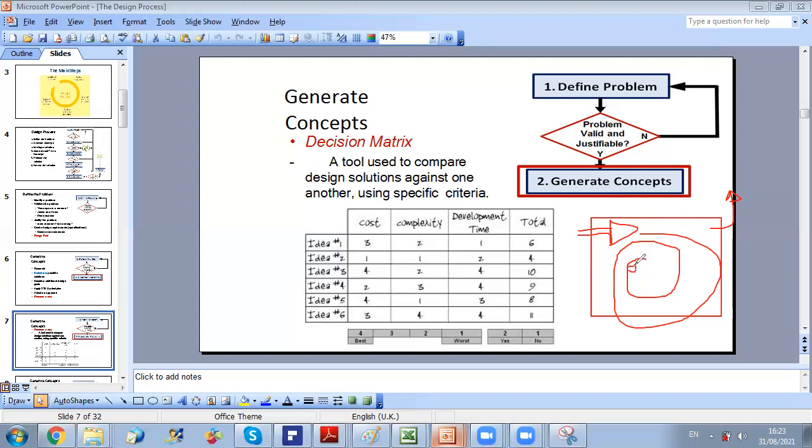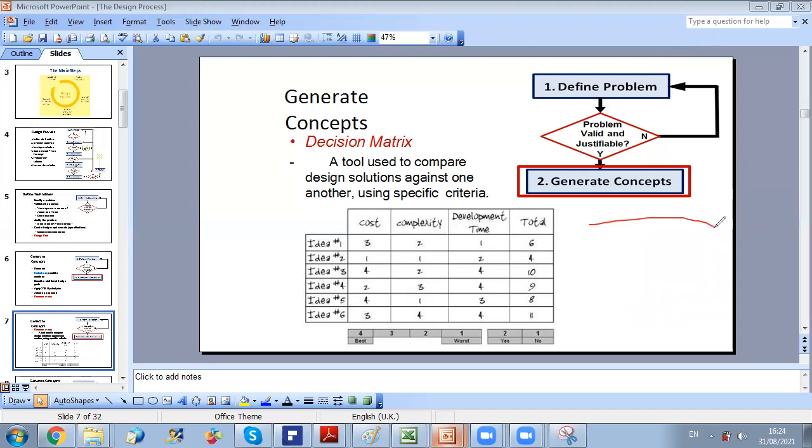Let's say you have two occupants here, and one is generating contaminants. Because of this mixing action and turbulence level, the viruses can be easily transmitted to the other occupant, which is bad. So let's say we want to come up with new ideas. So we can say that let us replace this system or maybe assist it with new systems. For example, one idea will be to use personalized ventilation.